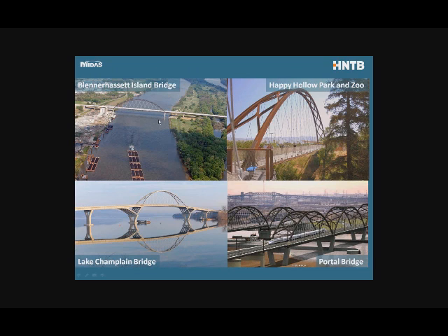So let me just run you through this, starting in the upper left corner. Here's the Blennerhassett Island Bridge. That's an 878-foot span, 100 feet wide. This is Blennerhassett Island. As far as I know, this is the longest span bridge in the world if you stick with the network-tied arch definition. You can see it very nicely. We have the inclined hangers, and each hanger crosses another hanger at least twice. There are longer span bridges in the world where the hangers don't cross. They're still inclined but don't cross, over Kampen or Rotterdam, for example.